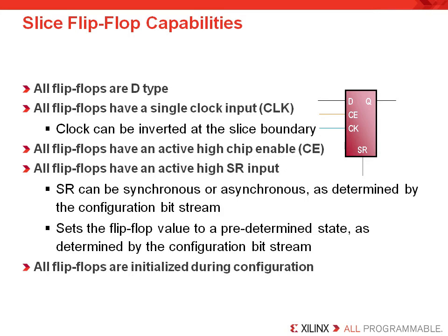The key is to realize that these tips will allow the implementation tools to group more logic together into slices, which allows greater device utilization and gives the implementation tools the best opportunity to find a better placed and routed solution that both meets your timing or performance objectives as well as higher device utilization.